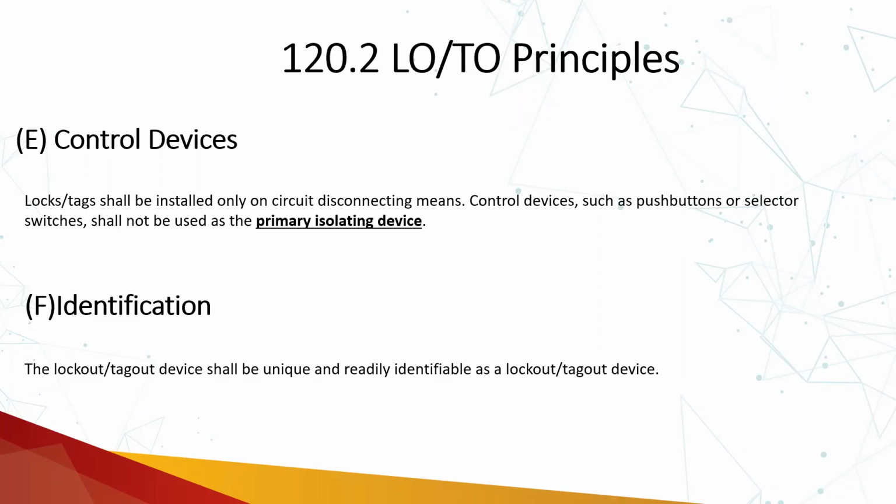Right? So normally I can use another type or color of lock in order to indicate that access is required in order to enter this particular substation or area, and this is not under lockout and tagout. This is only for security, theft, and other reasons.